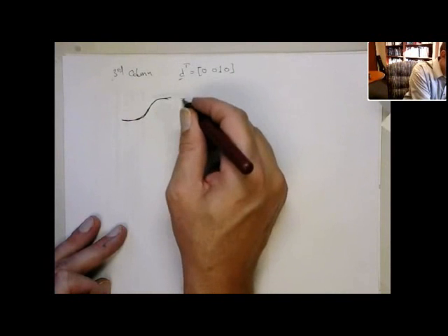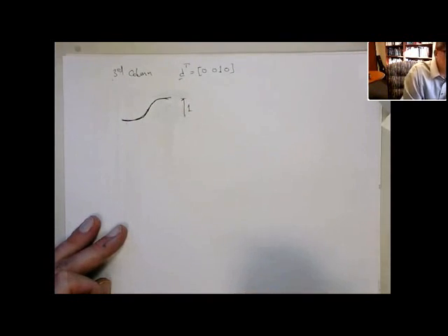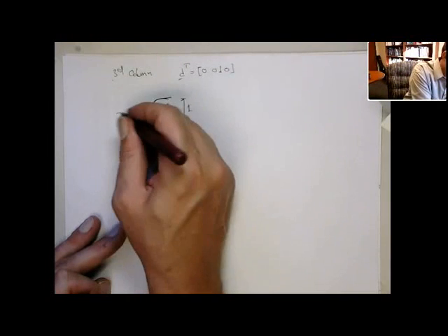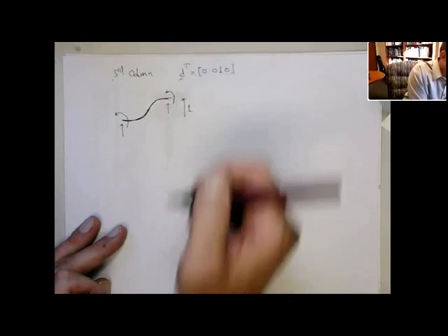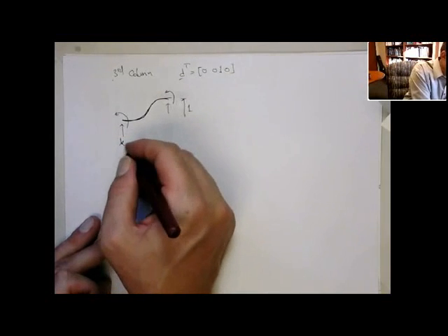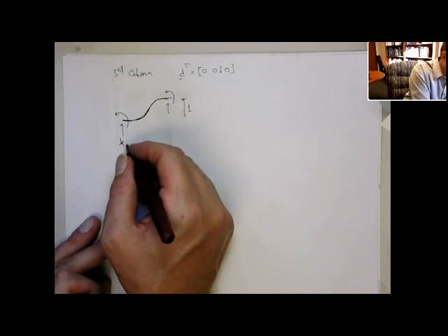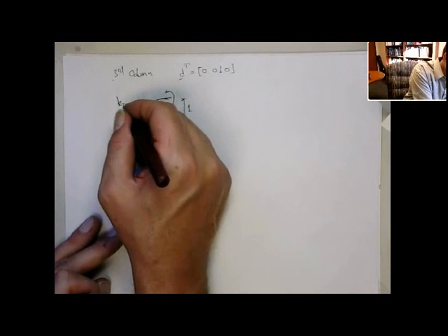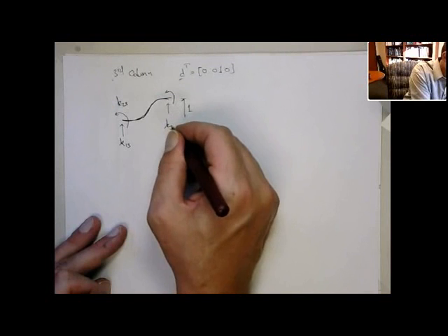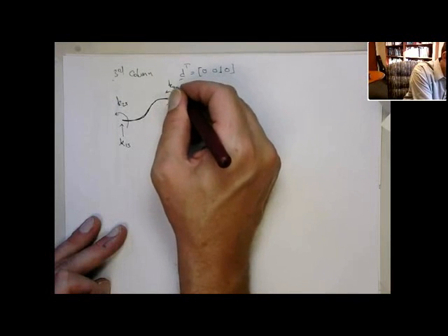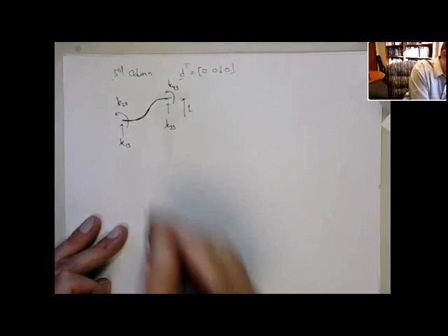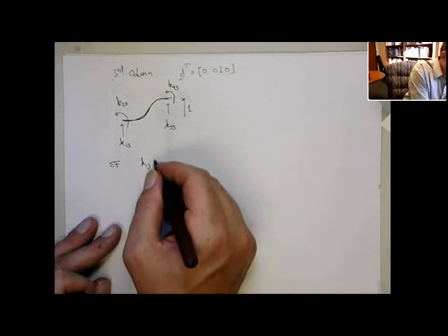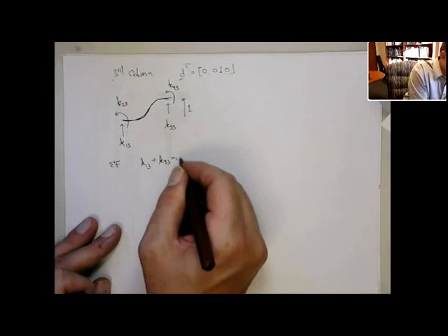So this displaces by 1. We know the rotations are 0. Now, again, we do the same arguments. We multiply through, and this allows us to get that the up force is going to be the K13, K23, K33, K43. All right? And again, we do sum of forces in the Y. That gives me K13 plus K33 equals 0.